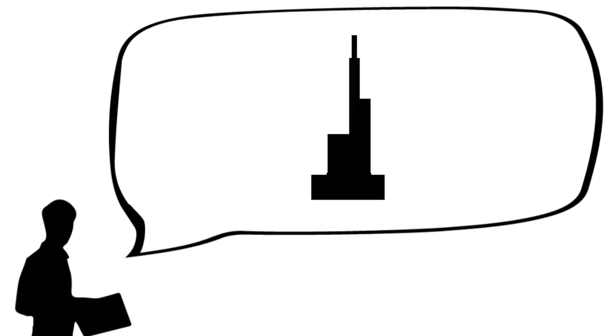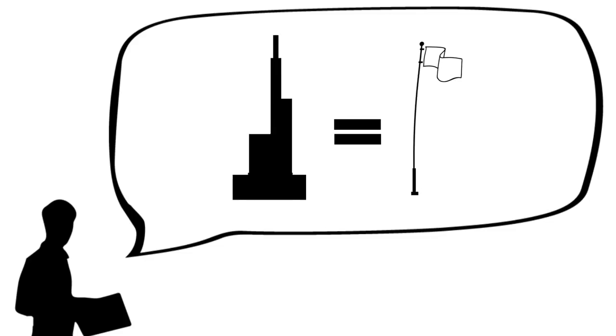Now, I just gave an in-person seminar at AIA New York, and one of the participants asked, what about a really tall, slender building? Would that kind of behave like a flagpole at the scale of the building, if you were worried about buckling for the building? And the answer is kind of yes. But in practice, the buckling would not be the biggest issue. In other words, you'd be much more concerned about other things. First of all, buildings aren't quite that tall and slender like a flagpole. And secondly, there would be other factors for the building that would require beefier structure, and it would be unlikely that buckling would control. But yes, same principle.